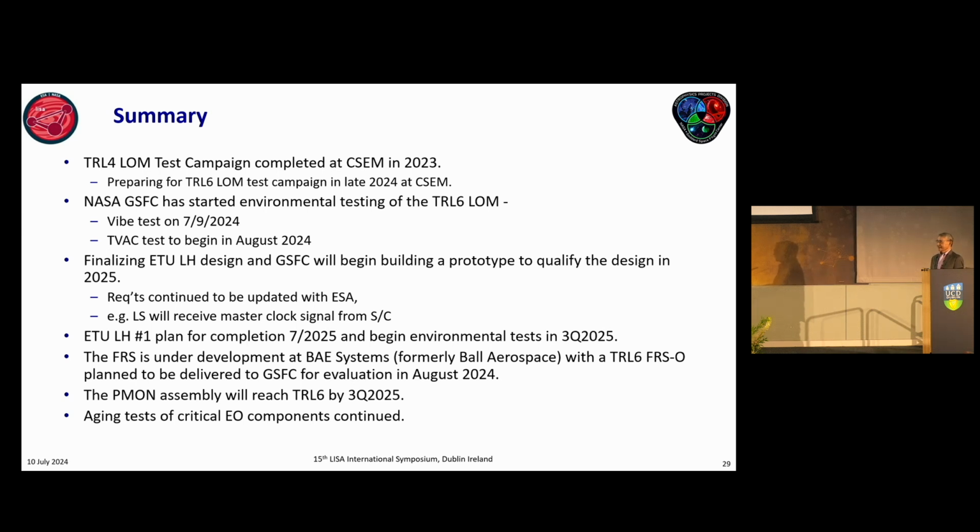This is really nice work. I just had a really quick question about the frequency test. When you took off the PZT, there still were some spikes that looked like they were above the requirement. Is that anything to worry about? Do you know what it's from? We believe those are from power line noise from the equipment, and we're going to make sure that we have a clean power source to run the test and make sure those won't show up. Got it. Thank you.